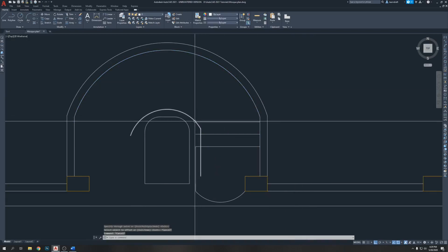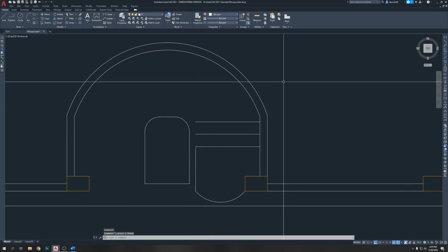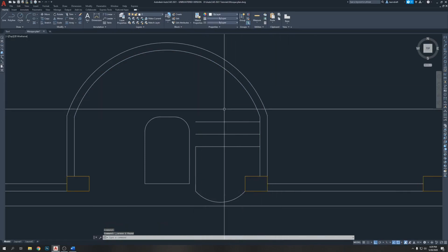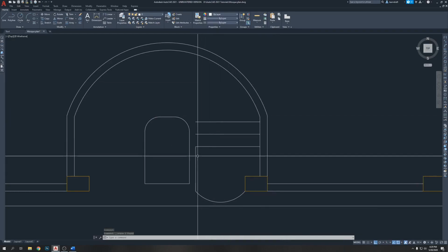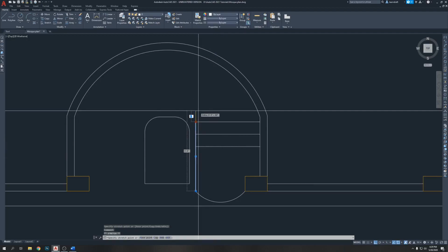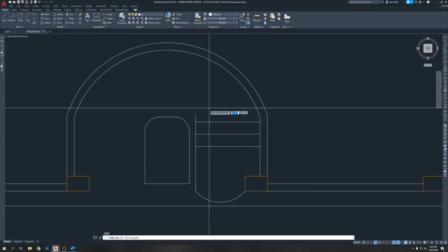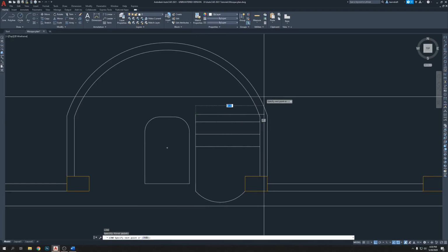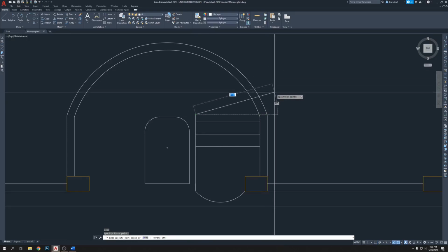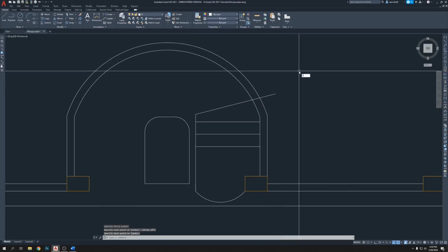Now, we do not actually need to do that. We need to draw a line which is this one, extend here, then make it 6 more inches, and then draw a line from here to, press F8. This is good. TR, enter.